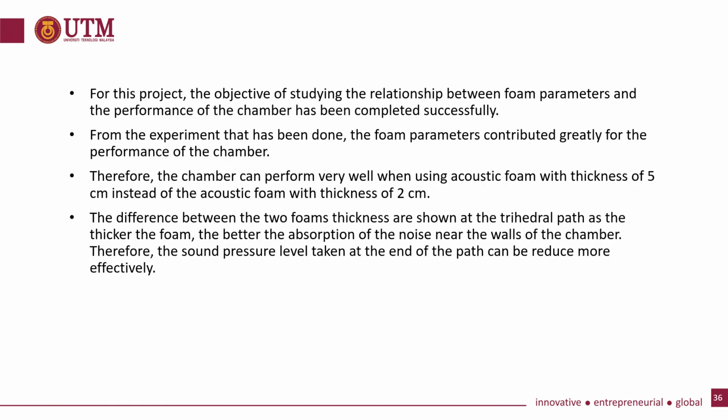For this project, the objective of studying the relationship between foam parameters and the performance of the chamber has been completed successfully. From the experiment that has been done, the foam parameters contributed greatly to the performance of the chamber. Therefore, the chamber can perform very well when using the acoustic foam with thickness of 5 cm instead of the acoustic foam with thickness of 2 cm. The difference between the two foam thicknesses is shown at the trihedral path, as the thicker the foam, the better the absorption of the noise near the walls of the chamber. Therefore, the sound pressure level taken at the end of the path can be reduced more effectively.